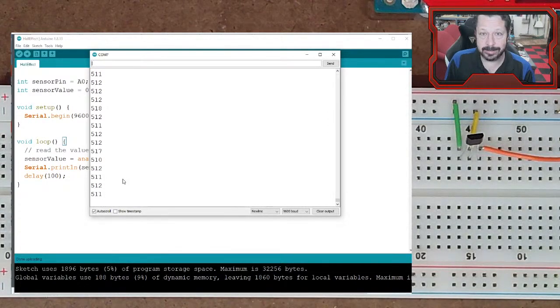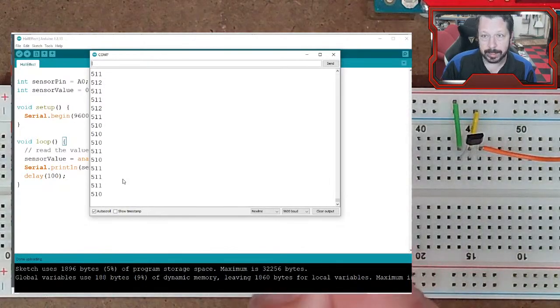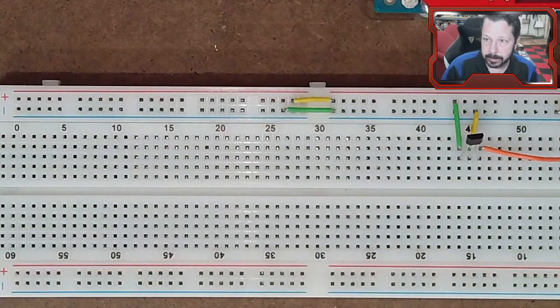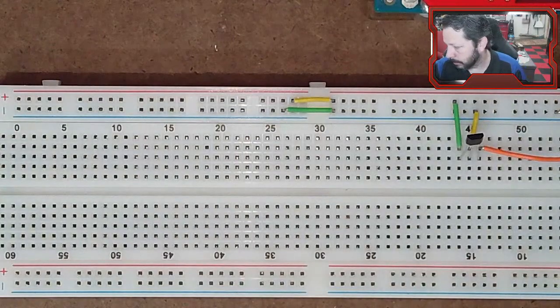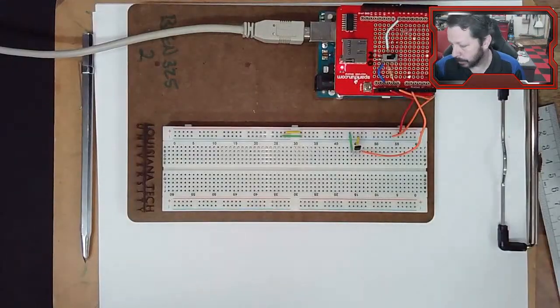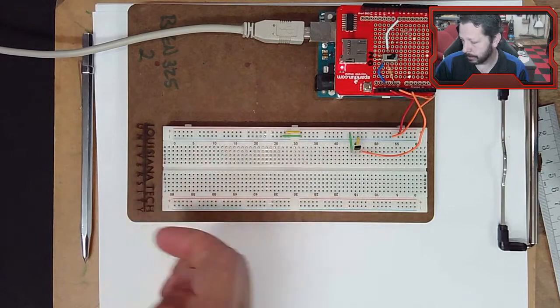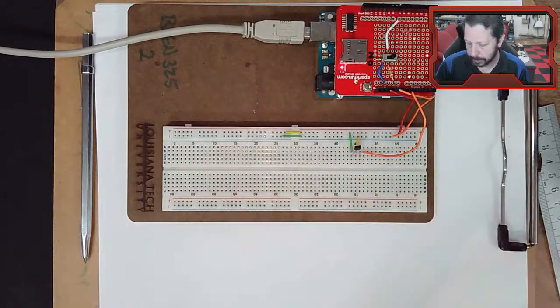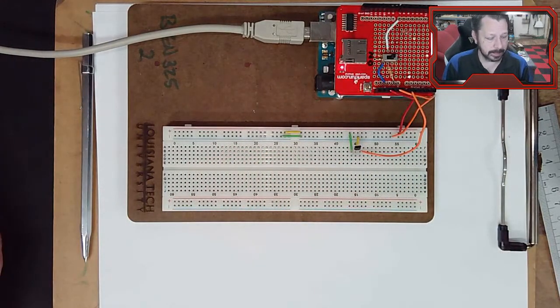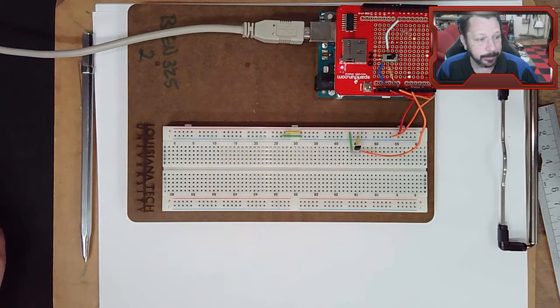You could just detect a level. The magnet could be attached to a float in water, and as it goes up and down, it could go past one or even an array of these Hall effect sensors, and as it goes past them, you can detect its position. A lot of different things you can do with these, and they're really simple and they're really cheap.